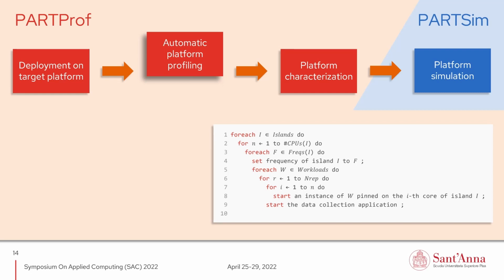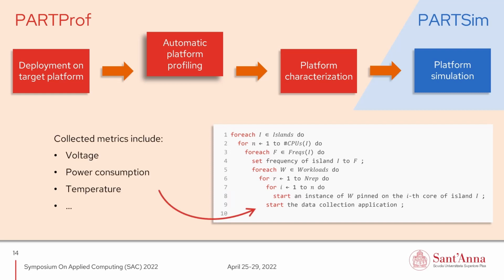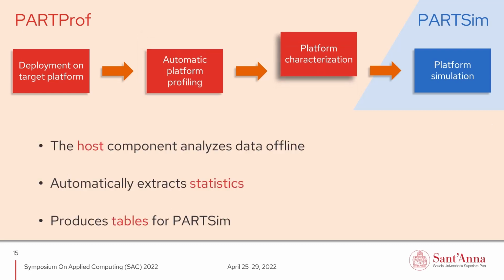For each of those combinations, it profiles task execution under those conditions, collecting several metrics over time, namely execution time, power consumption, system temperature, and so forth. Once all data has been collected, the host component analyzes it offline and automatically extracts a set of statistics used to drive the simulation of the power and timing of those workloads within the simulator.